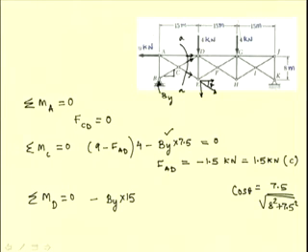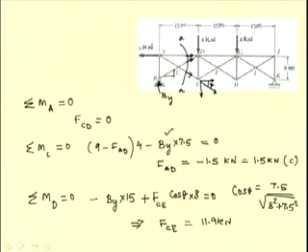7.5 divided by root of 8 square plus 7.5 square. So, the horizontal component of this force is going to have a counterclockwise moment. So, it is a positive quantity FCE cos theta, and the moment arm is 8 meters, and from this equation we determine FCE as 11.9 kilonewton, and since this is a positive force, it is a tensile force. So, this problem illustrates how we can use this method of sections to determine the forces.